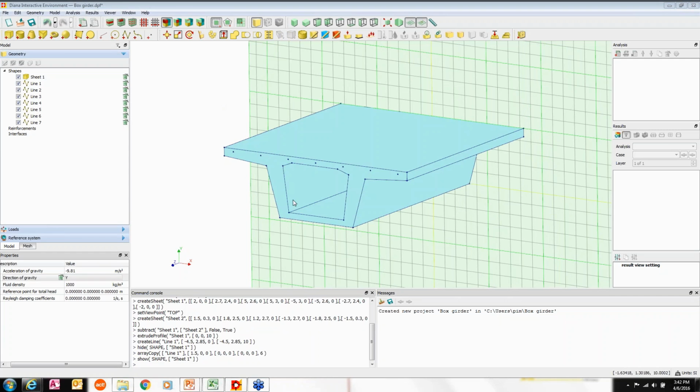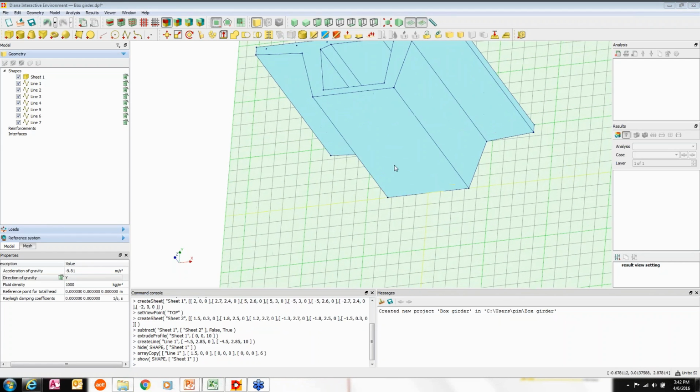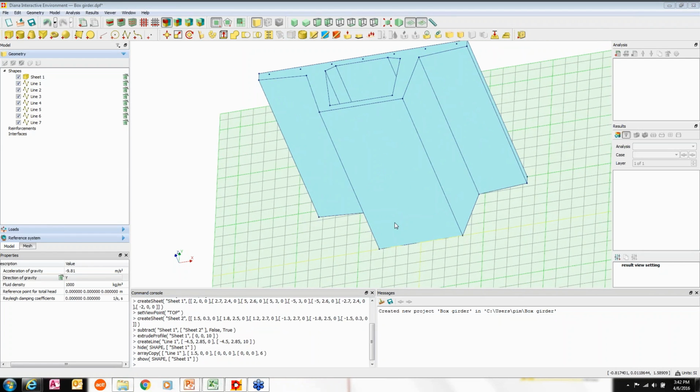So the next thing is defining the position of support. To create a support, I make one single plate, I copy them, multi-array position the 4 bearings, and then imprint these slabs or these faces to the bottom of this box girder. So let's do it together.